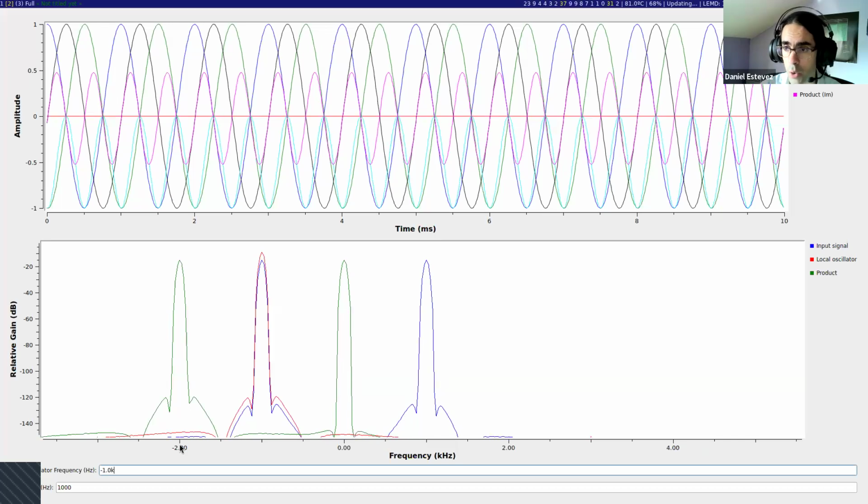So you basically have the cosine and the sine generated as local oscillator. Both of them are multiplied with the real input signal because the input signal is the voltage at the antenna connector. That is a single real signal always. And we generate a real and imaginary part for the product. And those are the voltages on two different wires.